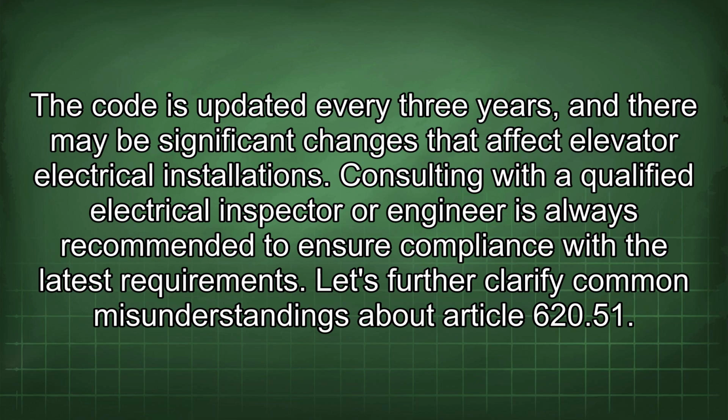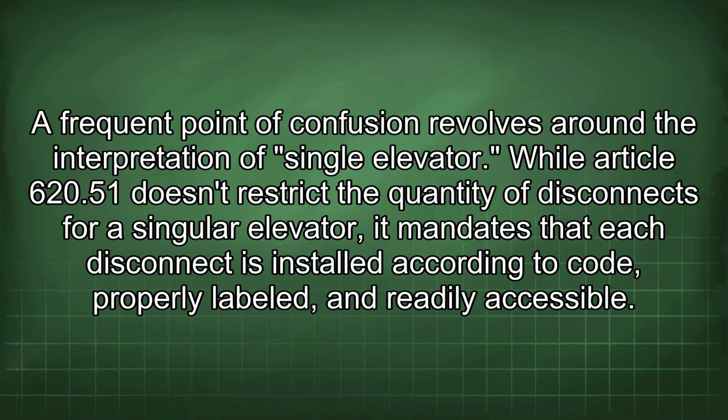Let's further clarify common misunderstandings about Article 620.51. A frequent point of confusion revolves around the interpretation of single elevator. While Article 620.51 doesn't restrict the quantity of disconnects for a singular elevator, it mandates that each disconnect is installed according to code, properly labeled, and readily accessible.